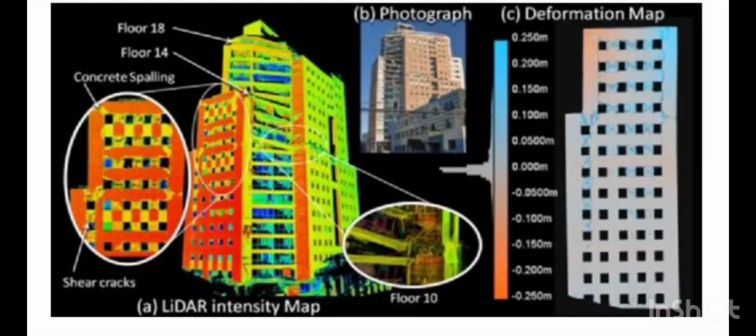3D surface modelling showed that 20% of the concrete and brick on the south face had spalled, cracked, or fallen off. This occurred due to increased vulnerability to lateral forces due to vertical irregularities and lack of lateral stiffness.